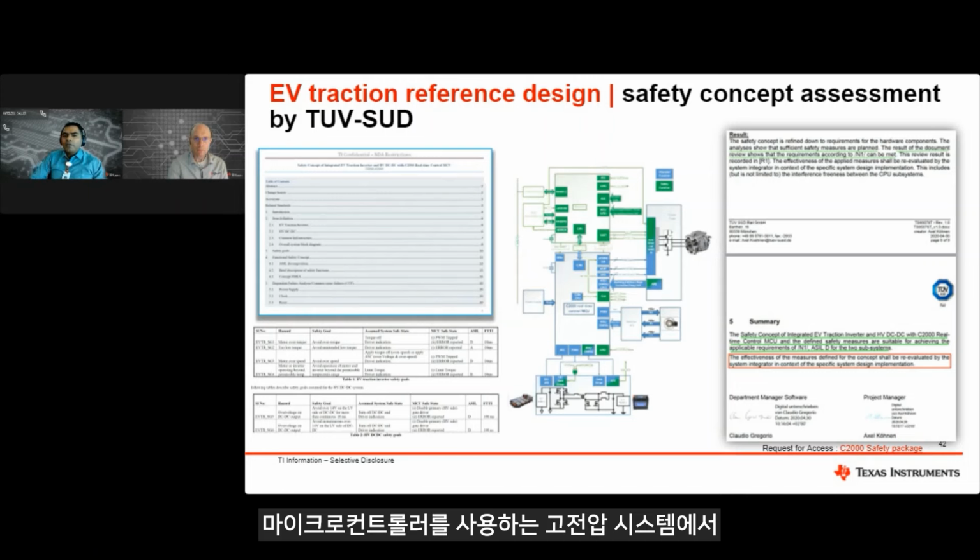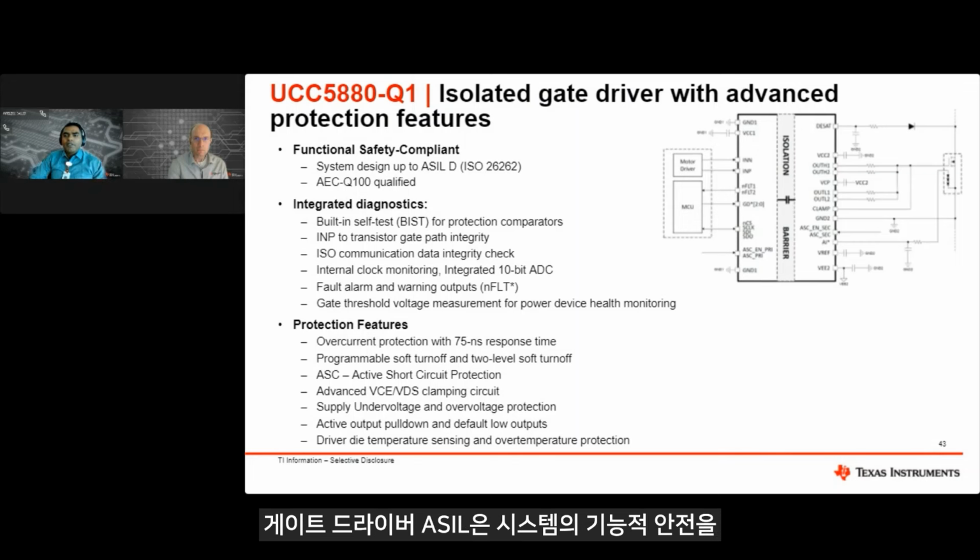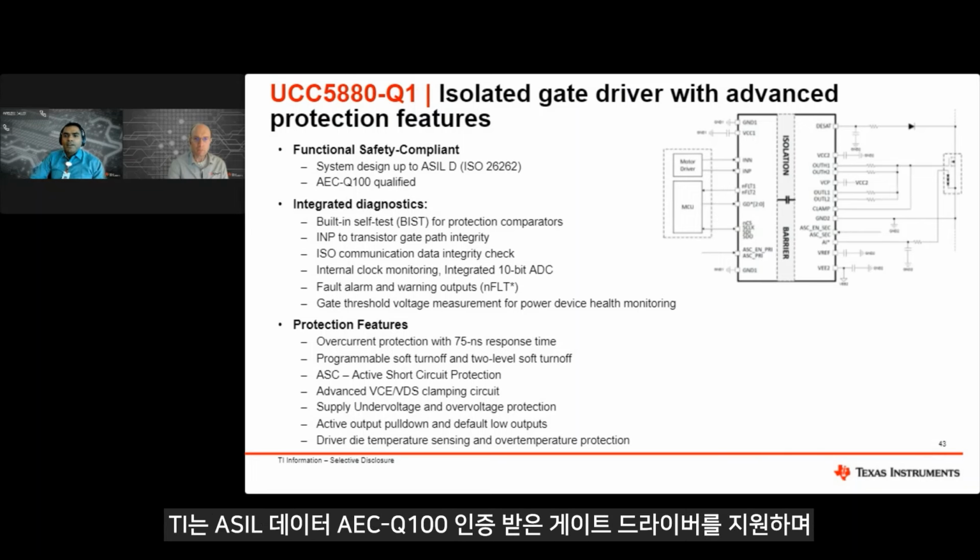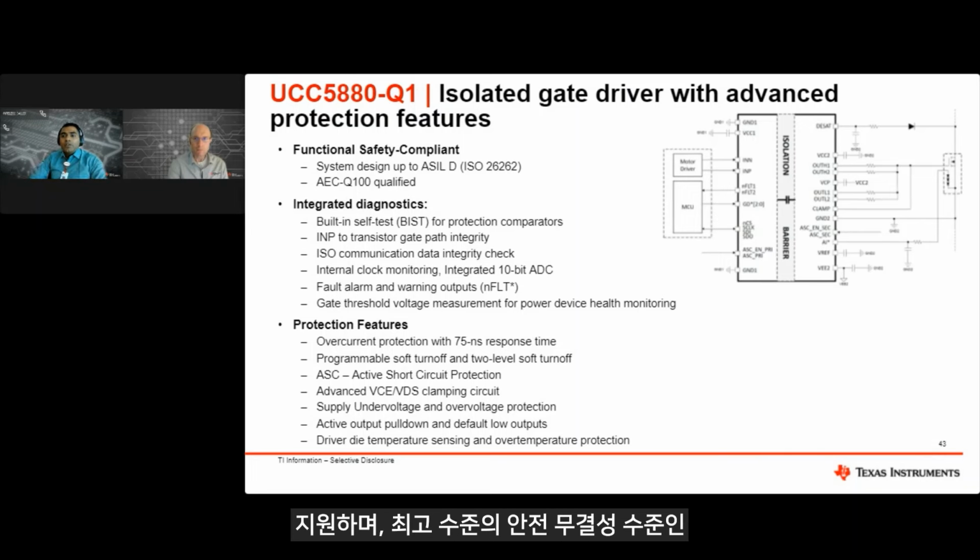In a high voltage system involving the microcontroller, the gate driver IC is a critical component to achieve the functional safety of the system. TI supports gate driver ICs that are AEC-Q100 qualified and can support system design up to the highest level of the safety integrity, that is ASIL D.